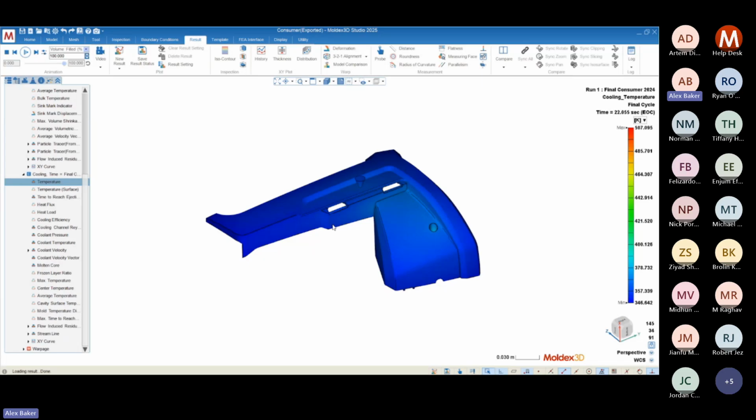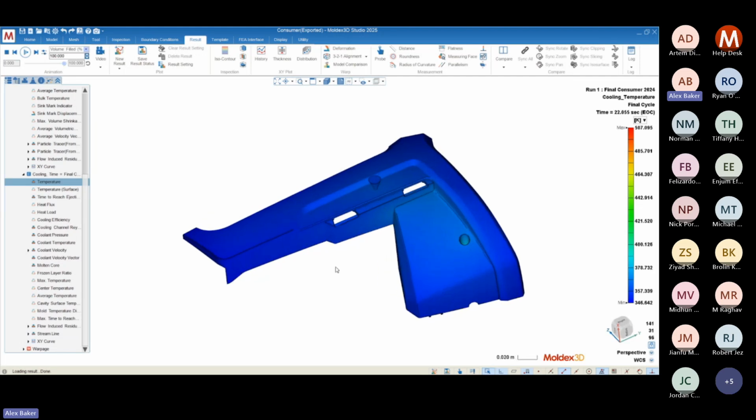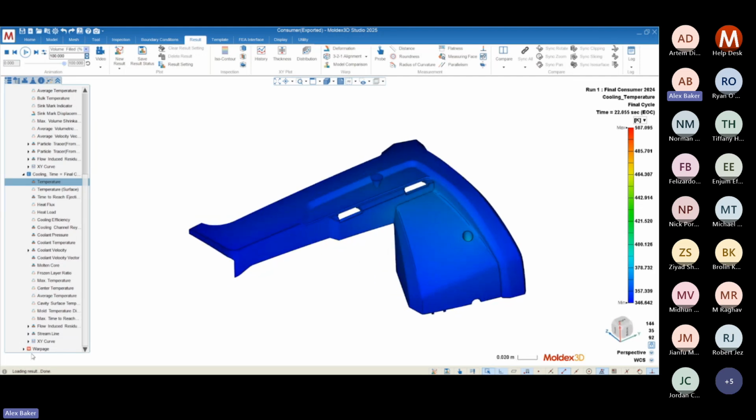And that's a huge component to warpage. We'll end up getting a lot lower of a warpage number in the simulation than you might see in reality, and it could be misleading. You could go down a rabbit hole of trying to figure out why warpage is happening that wouldn't happen in reality, strictly because you didn't include a cooling system.